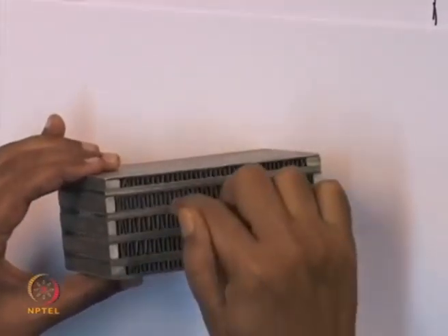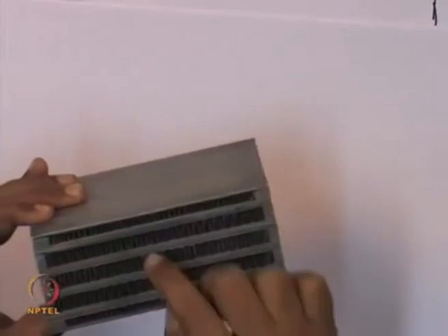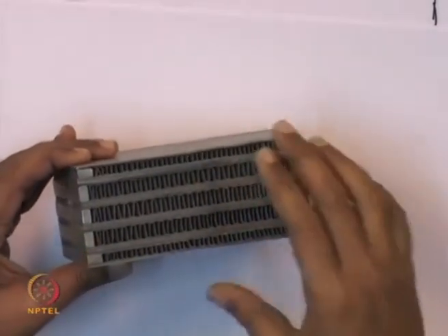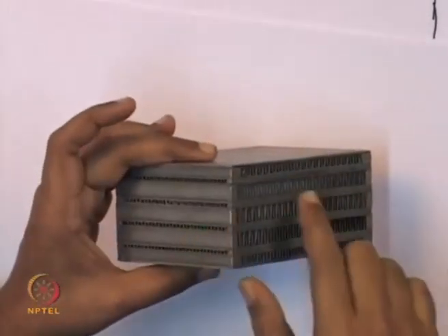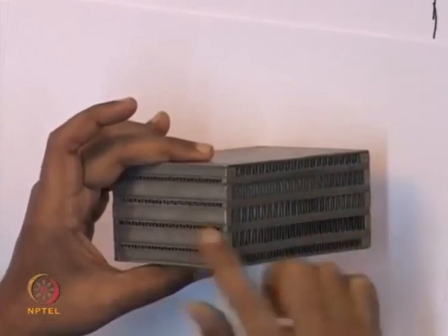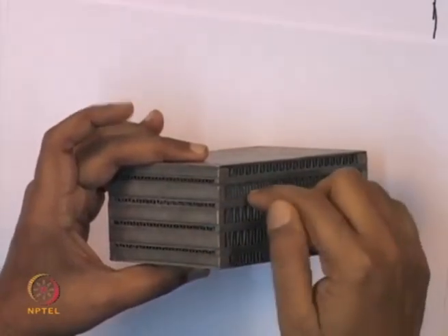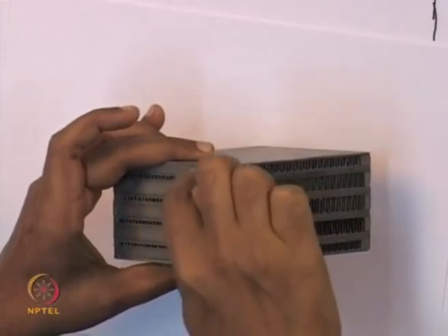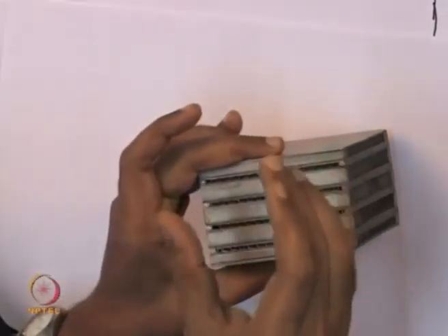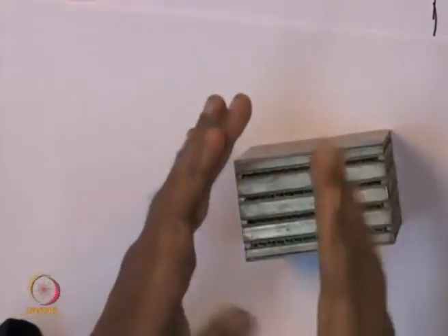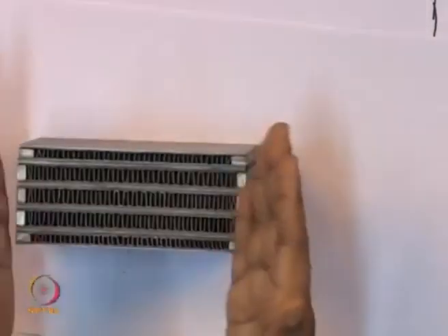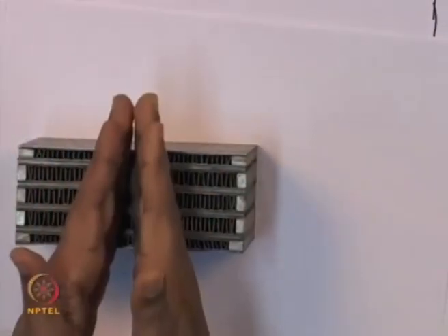So, one gas goes this way, the other gas can also come down from this if it is a counter flow. In this particular model, it is a cross flow arrangement. So, one gas is going this way and then in the alternate layer one gas is going like this. All these can have one gas coupled through a header, the gas can go in this direction, one header can be here and the other gas is going through another direction.